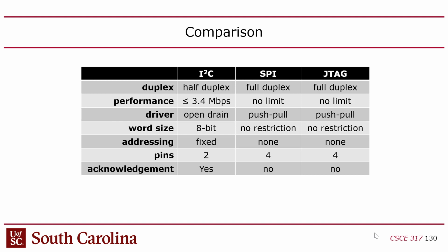So if we say set the dim period to a quarter second, it should go real fast, or we'll say set it to 5 seconds, it should go very slow. And then I keep saying piecewise linear. The pulse width modulation, the objective there is we want to know how slow you can make that before the lights start noticeably flickering. At some point, if the PWM is slow enough, you'll be able to perceive flickering. When do they start flickering? Because if you make it fast enough, it just looks like dimming, and they look like they're just on, but at a certain brightness level, right?